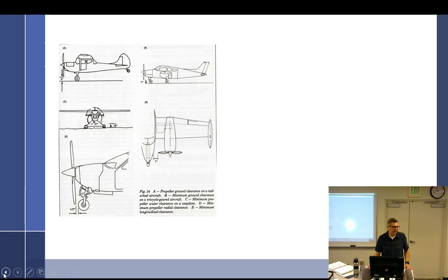Sorry, but it's more of a standard on how you create things. That's overarching about cars, motorcycles, boats. It's all of this now. And so as long as you're making it to these standards, then you're fine, which is why legally with these airplanes, you can go to the hardware store and get an SAE grade 8 bolt, because that's the standard that they're using. Instead of FAA standards where you have to have an approved PMA part. They're completely away from this now. Your legacy aircraft, Cessna, Piper, we don't fall under that, but these new airplanes, these light sports, they absolutely do.